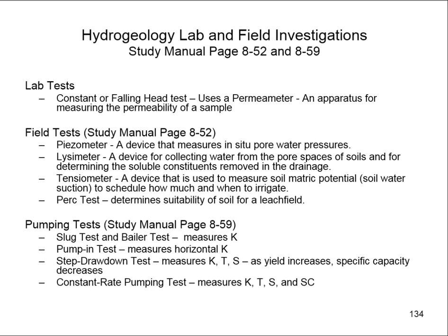When you're doing this, you have to be very careful about how you're sampling the material and how you're transporting it, because we're talking about coarse grain materials, and so the packing of those materials can change if not sampled and transported carefully. So you can get some wildly varying numbers of permeability depending on that.